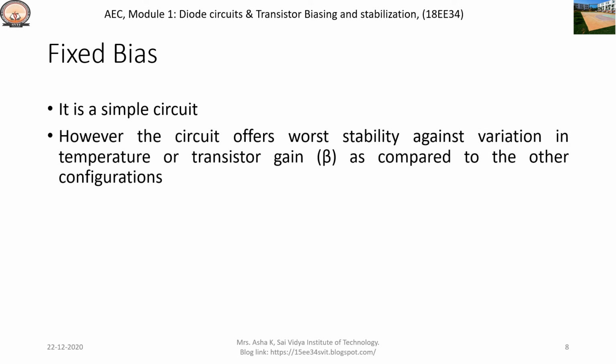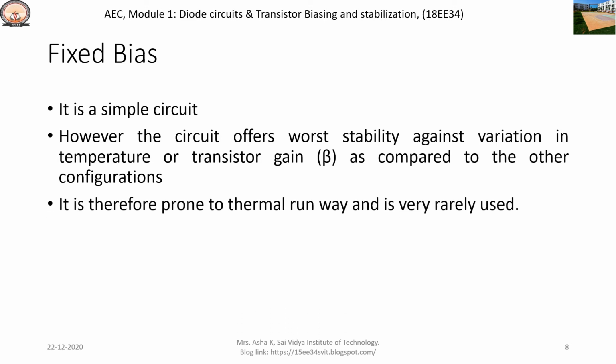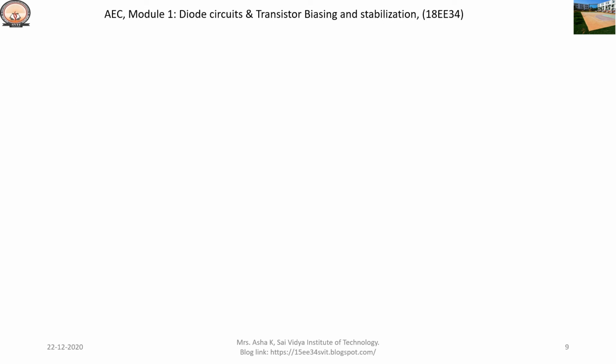worst stability against the variation in the temperature or the transistor gain as compared to the other configurations. It is therefore prone to thermal runaway and it is a rarely used configuration. We discuss the stability factor. Here, stability factor with respect to leakage current ICO.